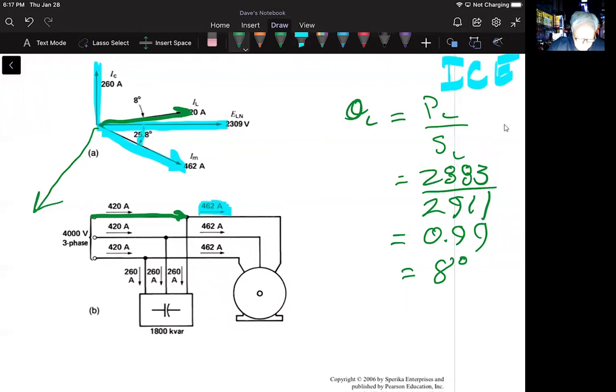The impedance values of the devices, such as the resistors, motors, and capacitors, seldom appear on the nameplate. This is to be expected because most industrial loads involve electric motors, furnaces, lights, and so on, which are seldom described in terms of reactance or resistance. They are usually represented as devices that draw a given amount of power at a given power factor.